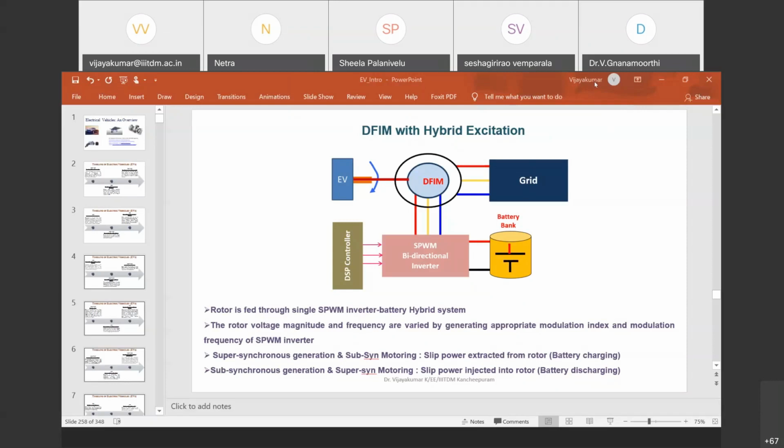Even in the future, for example, in a mobile, now we are using lithium-ion batteries, right? There are a lot of wearables, and in wearables the supercapacitor is going to play a major role. The same way in EVs and smart grid technology, we are going to use ultra capacitors or supercapacitors in parallel with the battery. Parallel with the battery means you are not going to connect directly in parallel. With a converter, you are paralleling it.